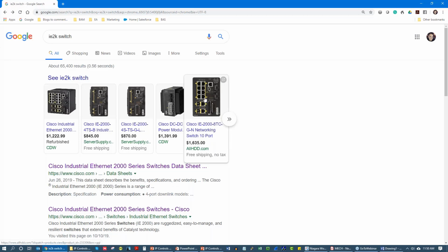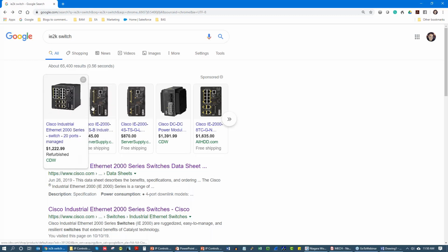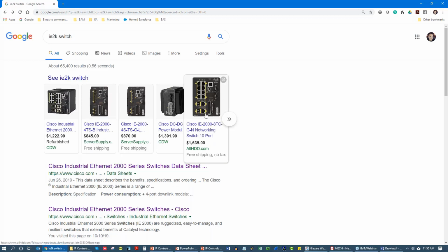And then if we do need to do a star pattern, let's say we have a lot of air handlers, we could run an unmanaged switch out of one of these ports and then connect all our star patterns into that. This is solely to host a network long enough to commission the building, make sure everything's mapped in.